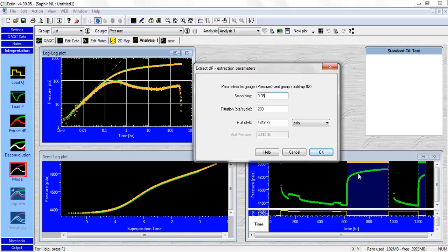Okay, so I'm going to repeat that. With a smoothing coefficient of 0, you will be able to spot some signs of wellbore phase redistribution during shut-in. You might have different phases in your tubing. Even if you've got single phase flow in your reservoir, you might have different phases in the tubing. And during shut-in, with expansion of the gas in the tubing, for example, or with natural gravity, these different phases are going to get redistributed, and the heavier fluid is going to fall down at the bottom of the well. So that means that the fluid density may change over time below the gauge.